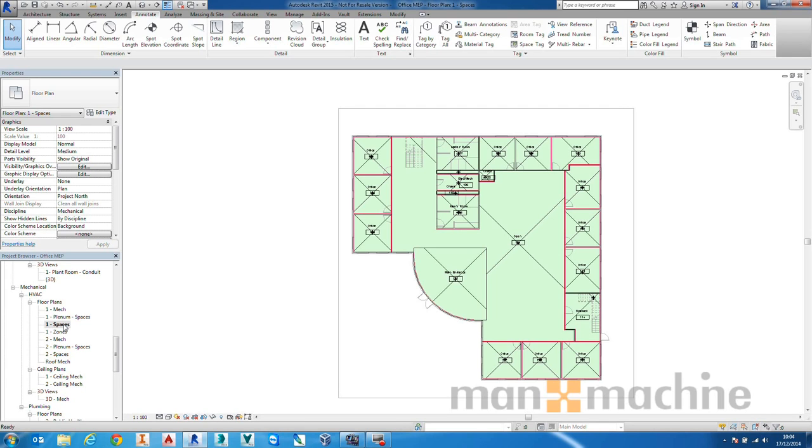So they'll be putting room tags on there and information about the size of those rooms, the area and the volume, etc. What the rooms are used for, for example. When we're looking at it from an MEP point of view, that information can be useful for us, but we're more interested in the use of the room, the size of the room, and then looking at potentially the flow of the room and what flow we need to keep that room at a specific temperature or with a certain amount of fresh air.